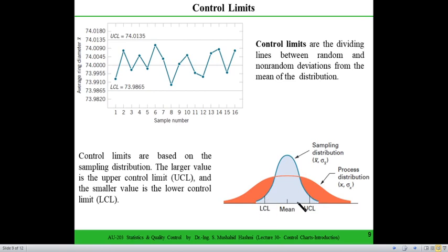If the area under the curve between the upper control limit and lower control limit is 99.7%, that represents almost the 3 sigma region. And if your process has a variation outside those control limits, it could be not due to inherent randomness, but due to some special causes.